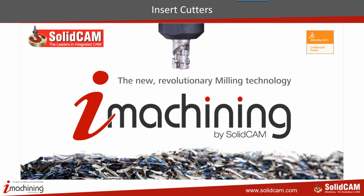So now, iMachining has two sets of technology wizard algorithms, each using a different set of parameters. One set for porcupine indexable insert cutters, the other set of algorithms for solid carbide end mills as before. For these reasons, we built a new tool table for porcupine indexable insert cutters. For the same reasons, we also built a new materials table.